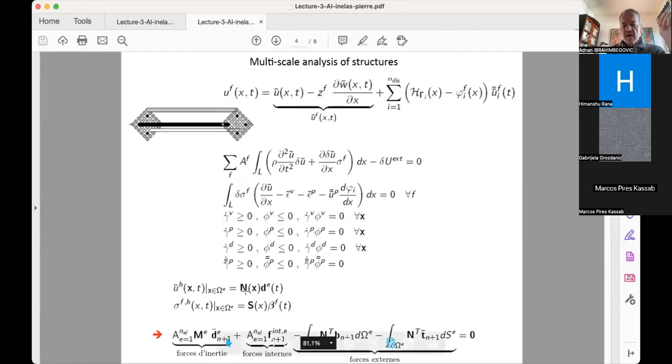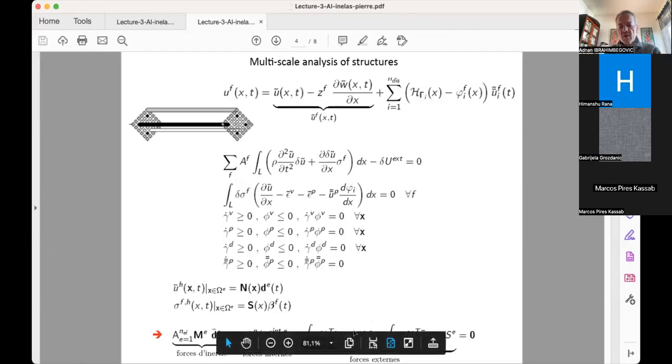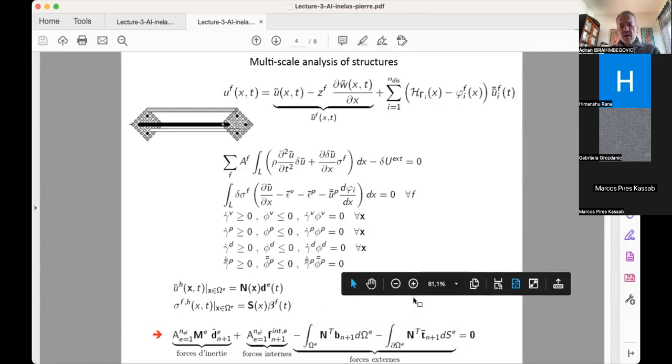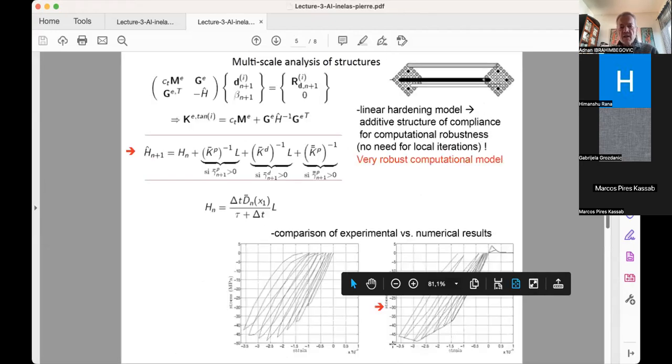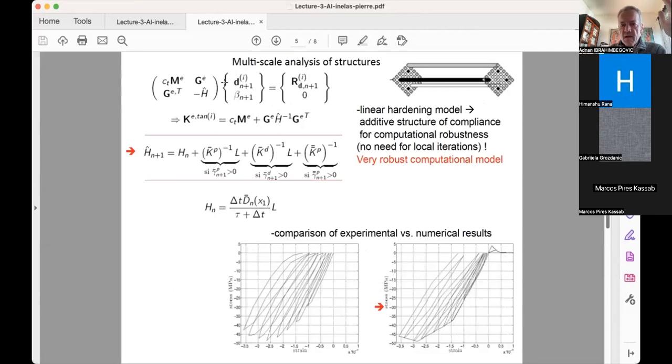So basically the idea is that I can run this computation. This is my equation of motion. Here is the inertial term, these are the internal forces that I obtained from discretizing this, and these are external forces. Then an extra term will give me the definition, this time around, not of the tangent stiffness. For any particular element, you can have this displacement, and you have this extra term for your stress parameter.